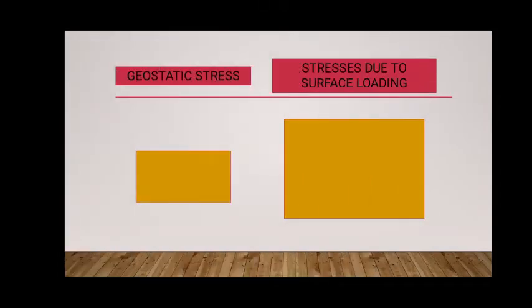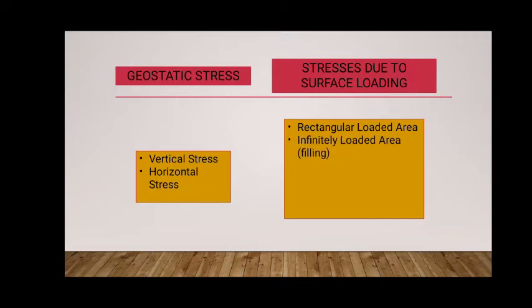For geostatic stress, we have the vertical stress and horizontal stress. For stresses due to surface loading, we have the rectangular loaded area, infinitely loaded area or the filling, the point load or concentrated load, and lastly the circular loaded area.